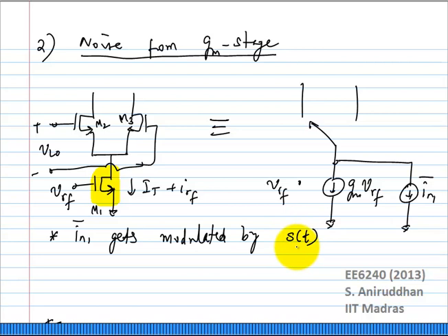First of all, what does this mean? When we say it gets modulated, obviously it is going to get, what? It's going to get shifted in the frequency domain. That is understood, right? So just as you shifted the RF signal from RF to baseband or IF, the noise signal will also get translated from RF to IF. Okay? So let us first look at thermal noise.